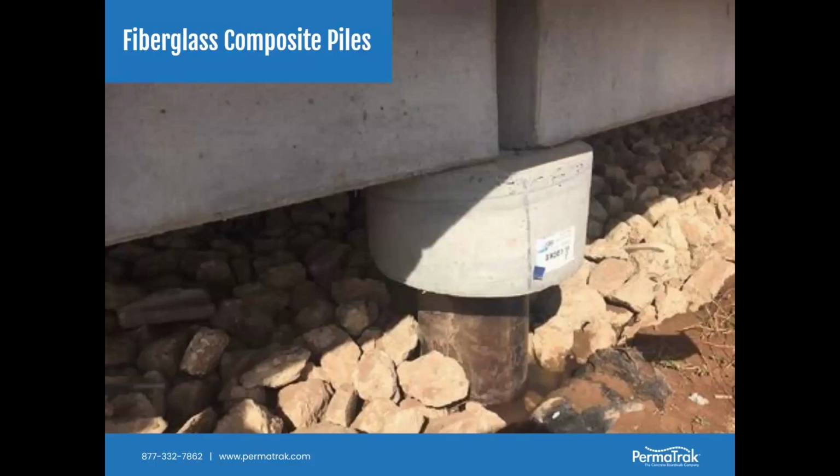They're going to be fairly light. They have a tremendous vertical load capacity, and they can be driven into the ground, because think about what they're used for. They're not being used for extremely heavily loaded bridges. They're being used for boardwalks, and the load requirement matches up very well with the capacity of a composite pile.